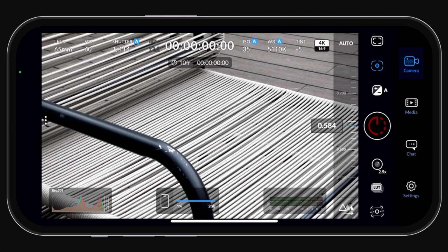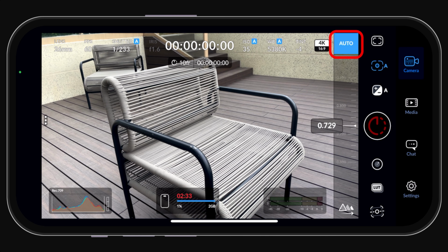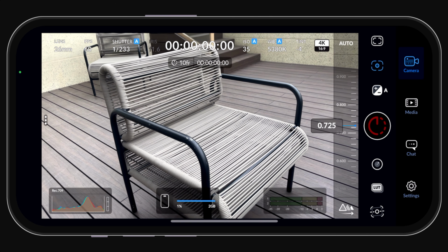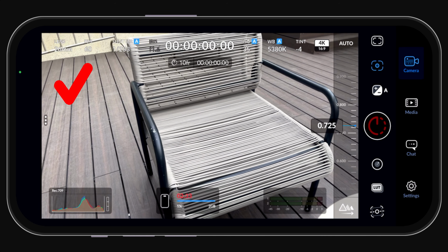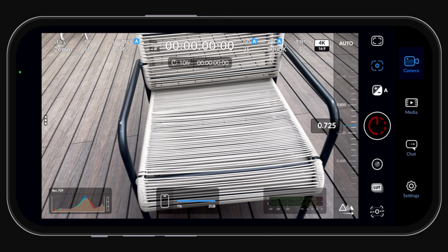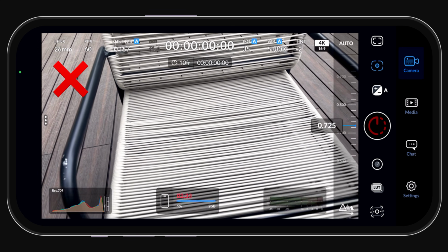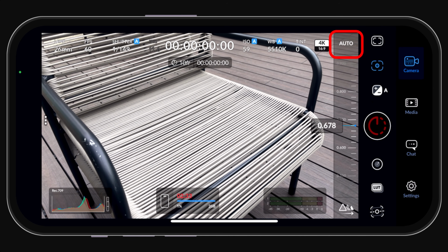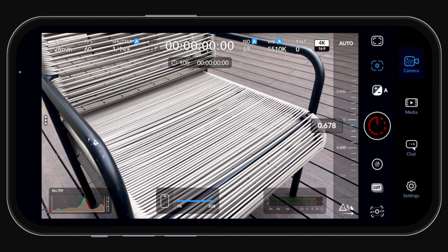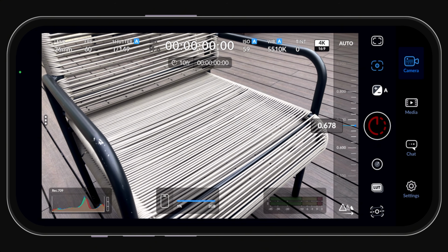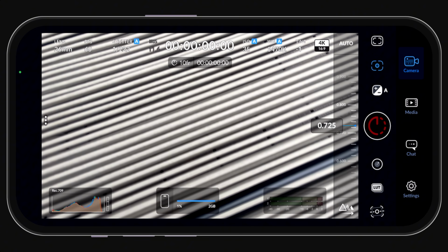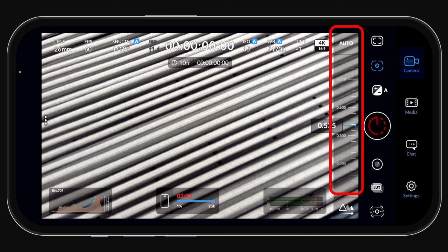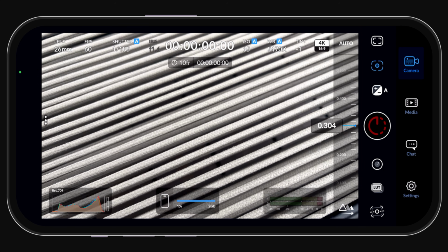We expect to keep camera parameters constant during the shooting process, so we need to fix a focus distance. Then, keep a close distance to shoot the object, avoiding large variations in shooting distance. To set the focus distance, you can first switch to autofocus and then cancel autofocus to lock the corresponding focus distance. If you need to shoot at different distances, you can collect data in multiple batches, using different focus distances for each, and then group the cameras during reconstruction settings.